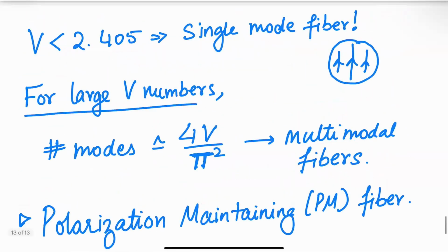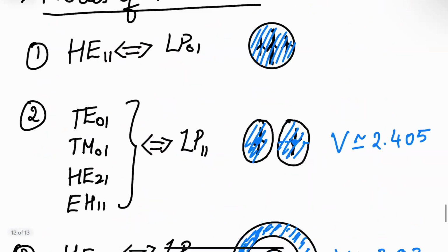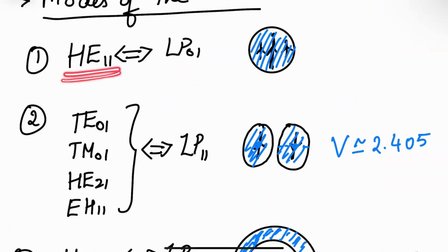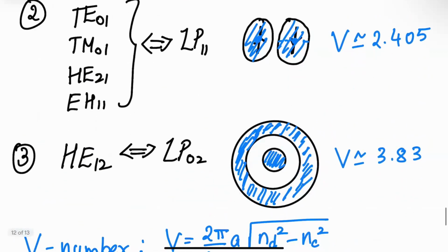Okay. So essentially, we discussed single mode fibers and what the main mode is, which is the HE11 mode, and this is the most popular mode when you want to do data communication, because you don't want different modes to propagate, because different modes propagate with different betas and different wavelengths, and it introduces severe dispersion, right? Also, if you want to maintain a Gaussian profile for your modal distribution, you need to make sure that it's a single mode fiber.